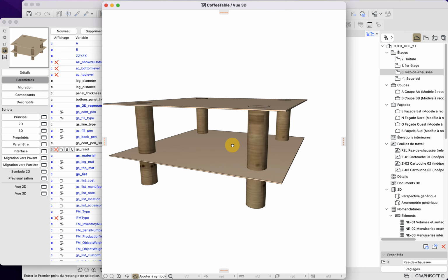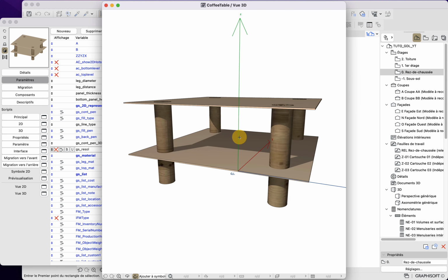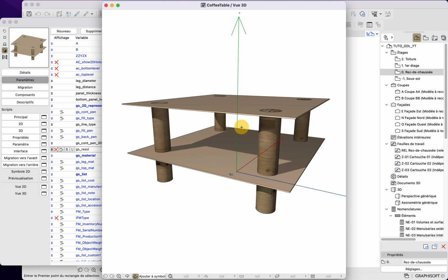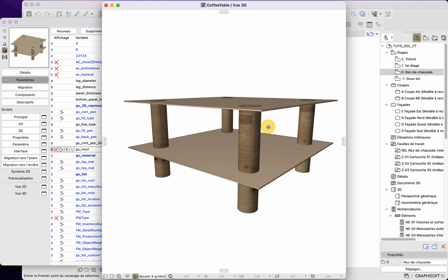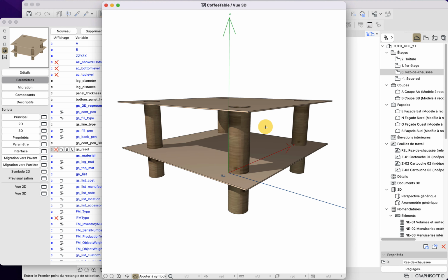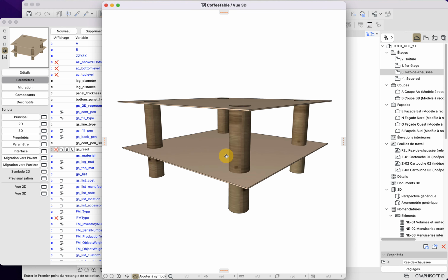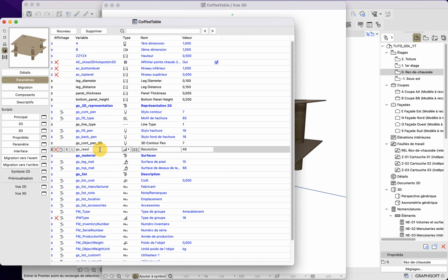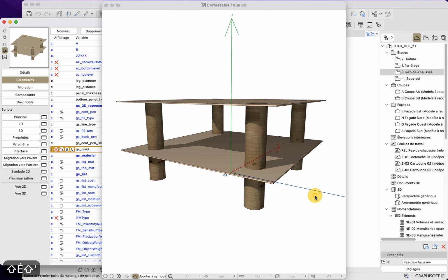Important to note, obviously, if you have more faces, you have more geometry, and if you have more geometry, you have more calculation when it comes to shadows, rendering, and manipulating your model. So it is important to have the proper balance between the faithfulness of the geometry and the size and efficiency of your model. By default, I put it at 24.